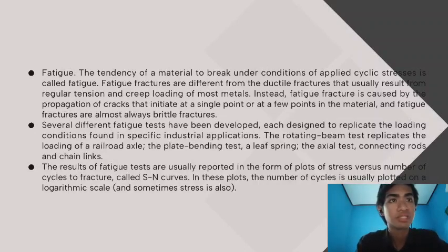Comparing the fatigue stress reduction factor to the theoretical stress concentration factor gives a measure of the sensitivity of the material to notches when under cyclic loading. Notch sensitivity is the fatigue factor defined by (Kf - 1)/(Kt - 1) and often is expressed as a percentage.